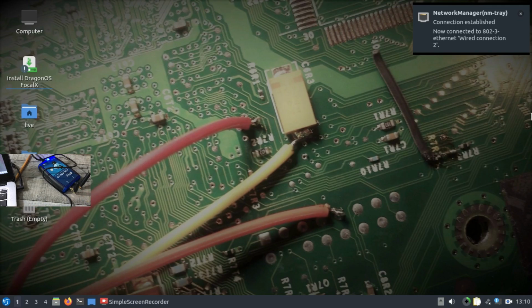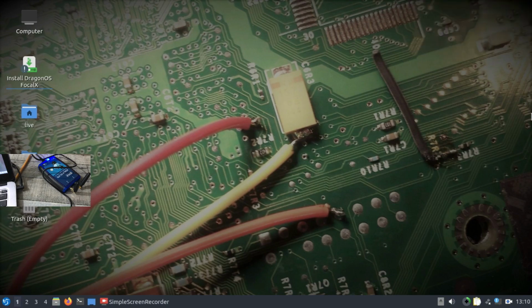I could have used HackRF, but the problem with HackRF is that it is a half duplex device, which means I can either transmit or receive. I cannot do it simultaneously. I can use HackRF to transmit, and then I can use an RTL-SDR dongle to receive. But the similar capabilities are there. But as you can see, the antennas are very close, so definitely there will be some noise issues. But just to give you a demo and what the capability of this software is, that's the purpose of this particular tutorial.